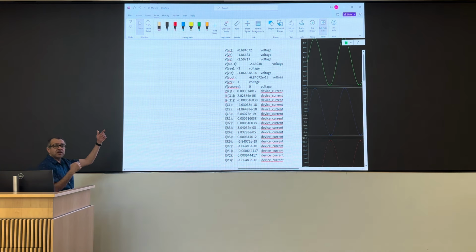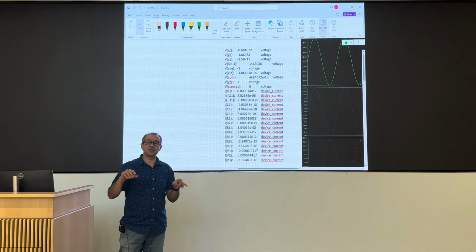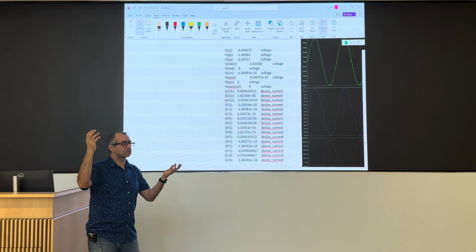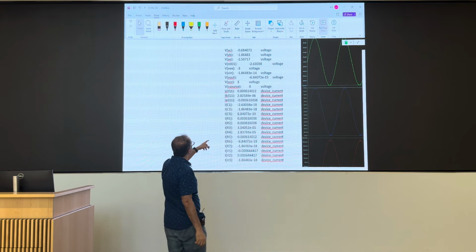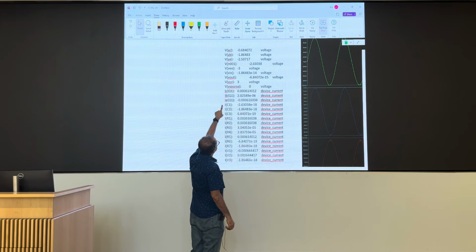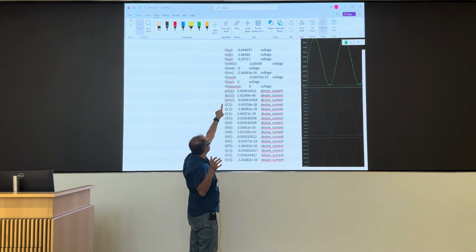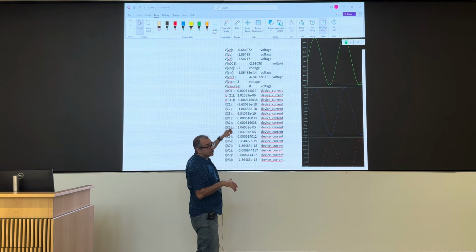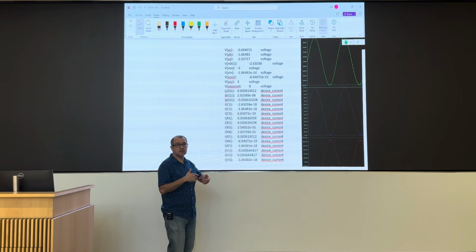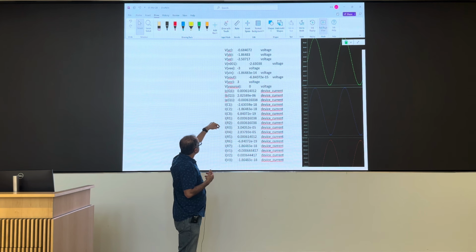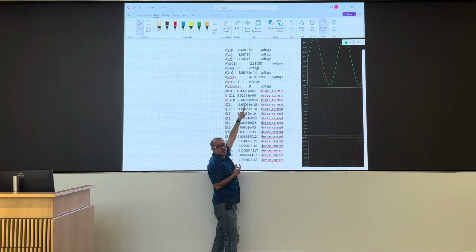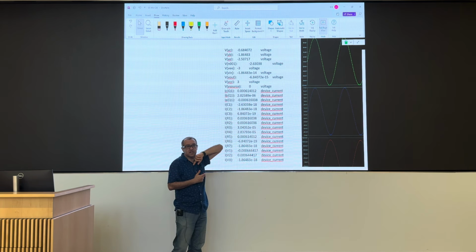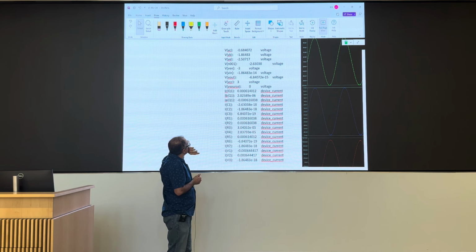So in LTSpice, you can look at the operating point parameters. The Spice directive is .op. It gives you the operating point parameters. So around that, the base voltage is 1.86, we said 1.8-ish. Collector is 0.68, we have how much? 0.65, I think. And then the emitter is 0.65 volts less than that. ICQ1, that's 614 microamps. And so we had something not that big, 605.